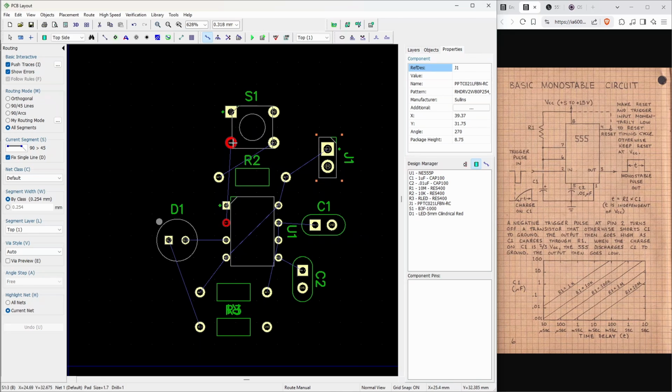But for this kind of board, it's sort of fun to make the connections and rearrange things in a way that is maybe aesthetically pleasing and also is functional, right? We don't want to have the button too close to this because the wires are going to be coming off. It'd be hard to push the button. Maybe we want the LED in a specific place because there's going to be 3D printing of an enclosure, all those things. So let's start making some connections.